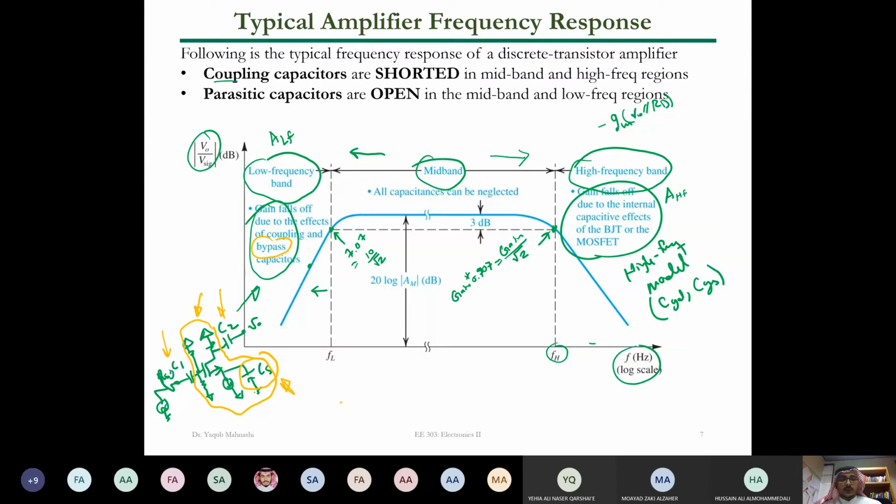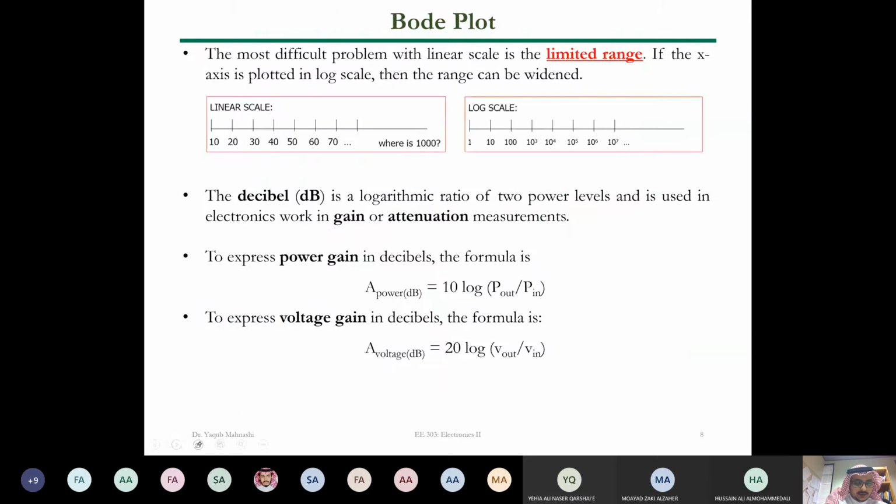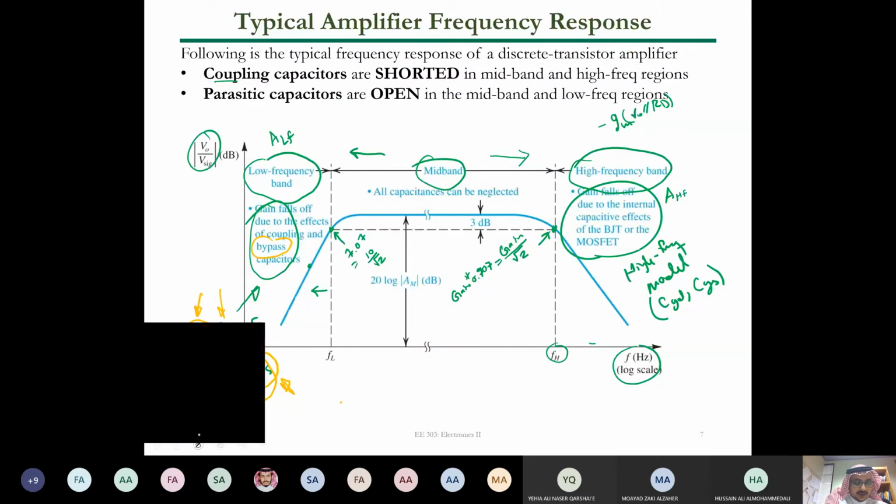By the way guys, why do we call it bypass? The coupling, we agreed, is joining the input and the output to the system or to the amplifier. Why did we call it bypass? Because we used it so that the source current runs from a DC point of view and is demolished from an AC point of view. Excellent. Let me put this one here again, let it be a resistor.